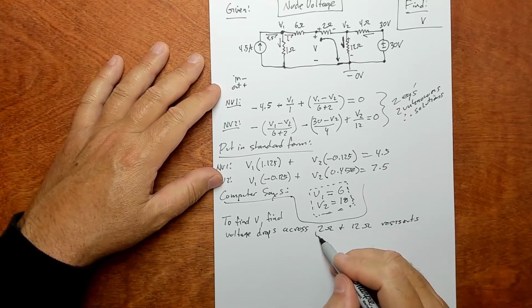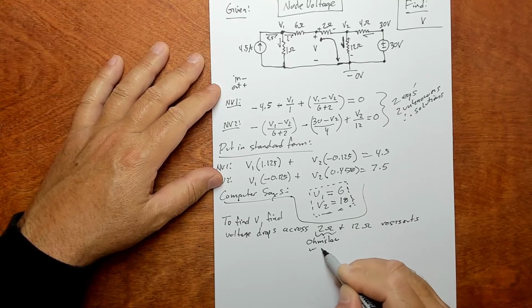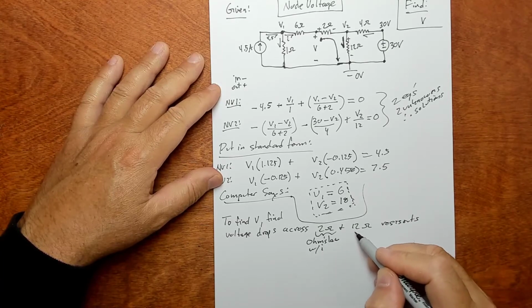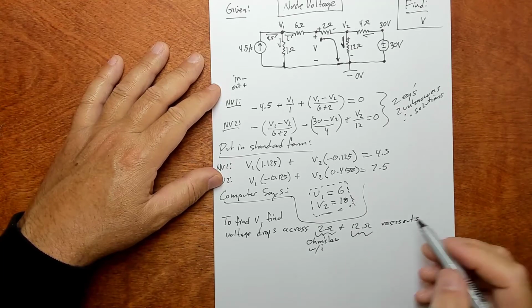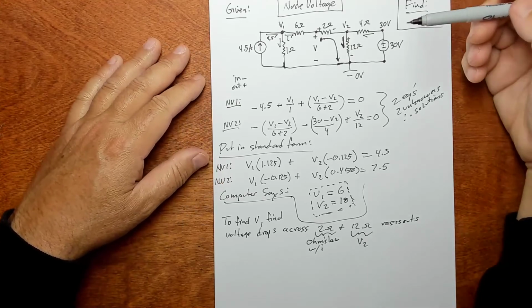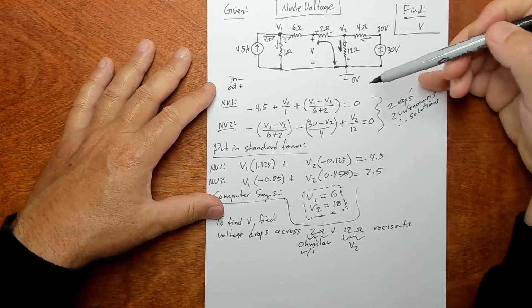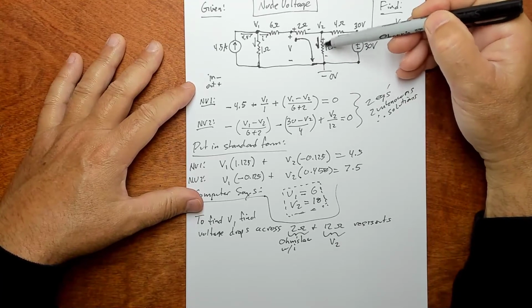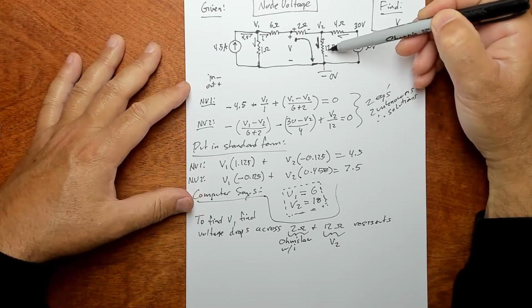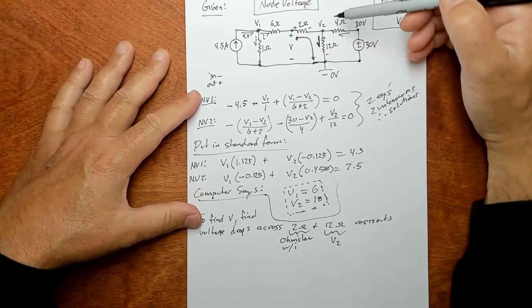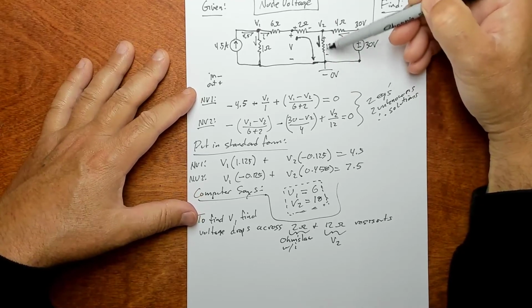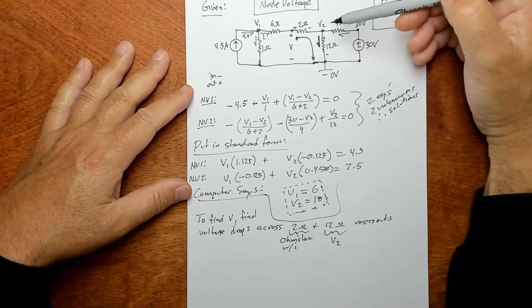And this guy here, I can use Ohm's law with I. And this here, this is just V2. I was saying just moments ago that if I had this current through here, I could use Ohm's law to figure out this voltage drop. But I don't even need to do that because I have V2, and that is the voltage drop across this.